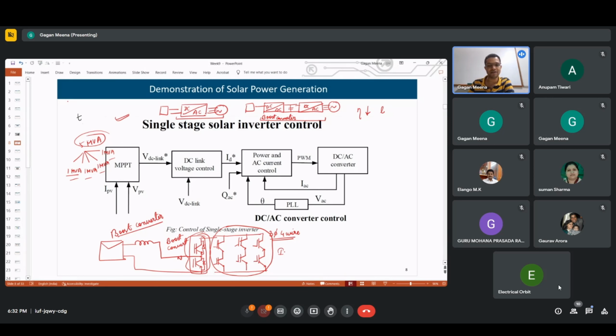These are the drawbacks for this DC fast charger. Higher current will lead to higher losses in charger and battery, which leads to degradation of capacity. Higher C rate also reduces the battery life because of excessive heat, thermal runaway. And fast charging, as I have already told, can reach only up to 70% or 80%. And thicker cables are required to allow more current.